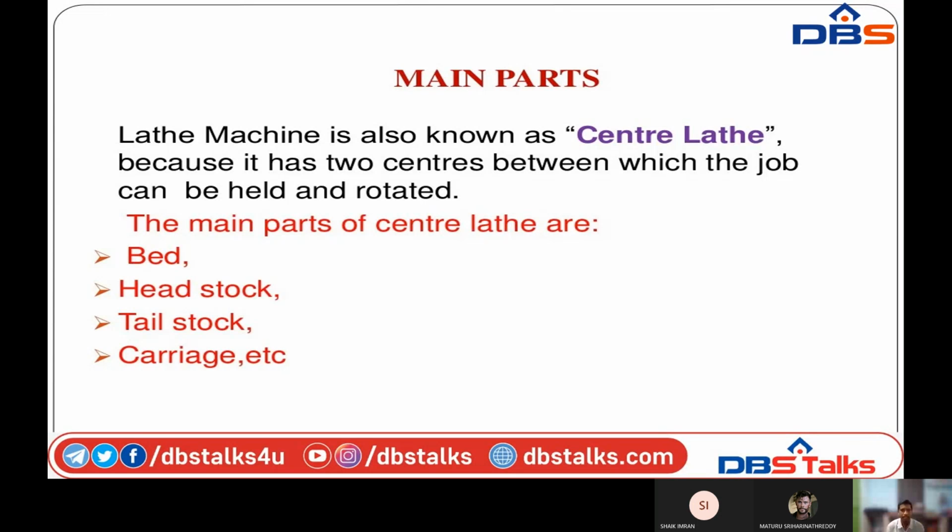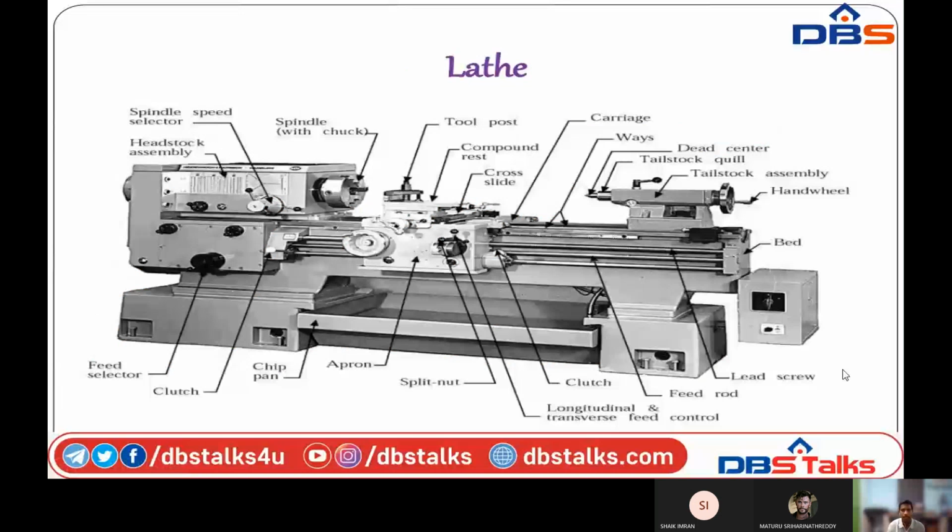I am calling the tailstock a dead center because the tailstock is just a support, just a support for fixing the tool. Next, carriage. Carriage consists of parts like tool post, cross slide and compound rest. Here I am showing the main parts of lathe machines. First of all, I am talking about the bed. On the right side, I am showing the bed here. The bed is just a support for all the components like feed rod and lead screw.